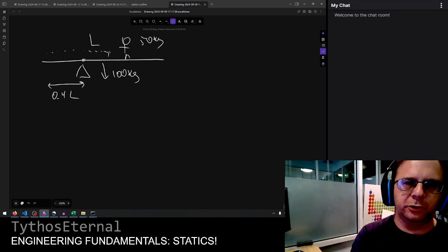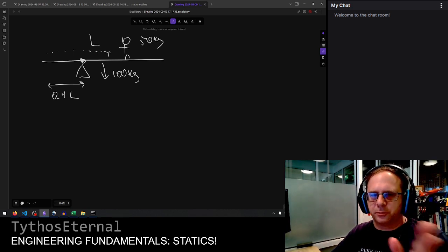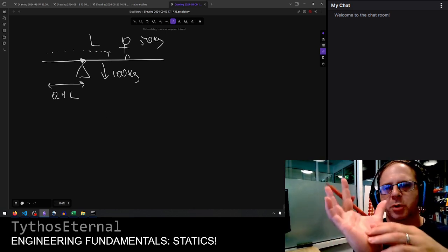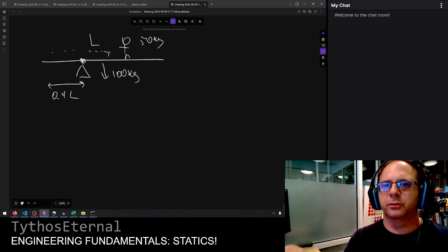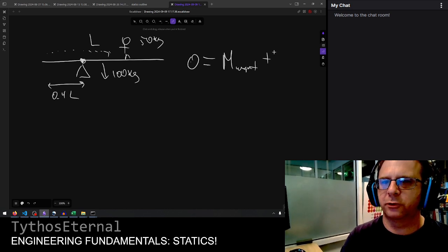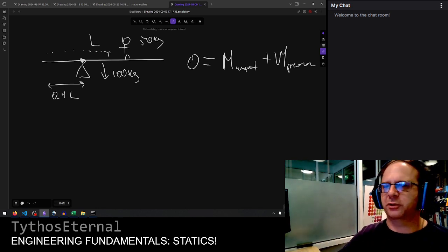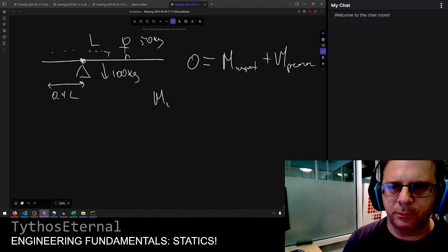We'll choose our system. Choosing our frame is always important. In this case, we'll choose the fulcrum as the frame, x displacement to the right, positive moments is right-handed about the fulcrum. So that lets us sum moments and say that we have two moments here. There's a moment from the weight of the lever and there's a moment from the person. And based off of the way we define moments, we'll be able to ascribe signs to those, but we know the sum is 0.